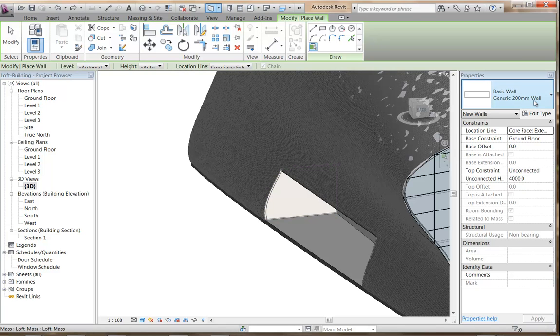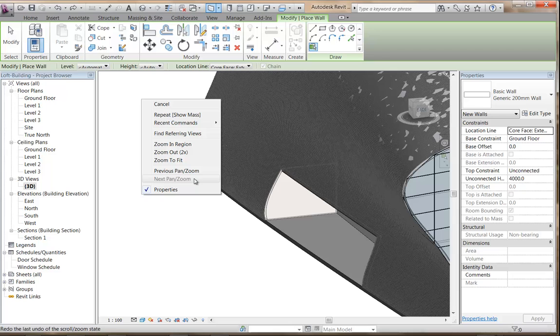So I've got my major project done in AutoCAD. Is it easily put into it? Kind of. Yeah, it's got import tools, but you've got to remember BIM software works in a totally different way to traditional CAD software. BIM software is still CAD software, but it's a different kind of CAD software. So is it mainly 2D that you've done in AutoCAD? Okay, so then you can import into different views, and I'll actually go through some workflows you can use for that, because when you import something from AutoCAD, you actually have tools in Revit, mainly for the views.